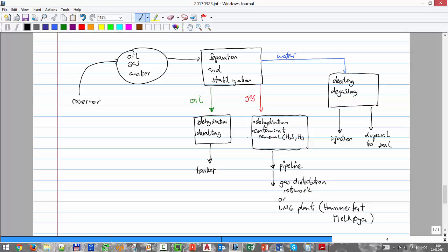But before that we forgot something else. To transport it, remember that we are at a low pressure. The separator is like the anchor of the whole upstream production system. I know that the pressure will remain constant no matter what. So that pressure is usually low, such that I cannot just plug the pipe into the line and have it transported. I have to compress it first. So here I have compression. And before injection, I might also have to do pumping.